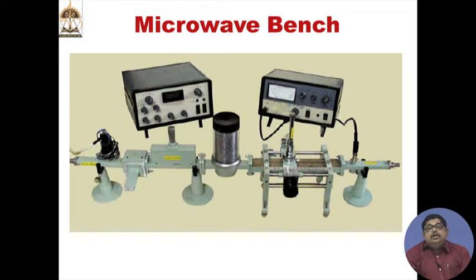But there is also a semiconductor counterpart, called a Gunn diode, whose power output is a bit low, but compared to a vacuum tube, a semiconductor is more rugged, that is why that also is used. So, here you can see on the left that black one, that is a klystron source.